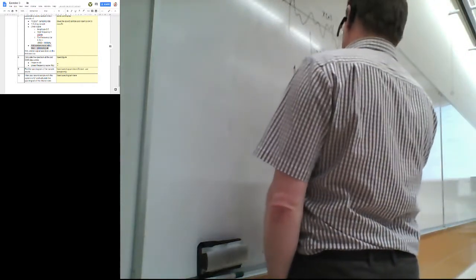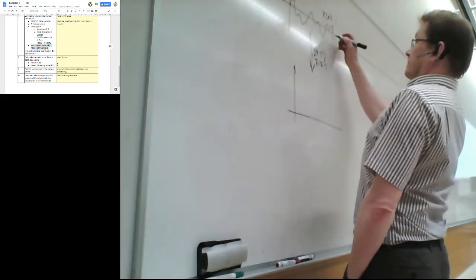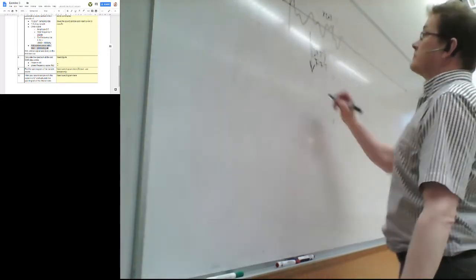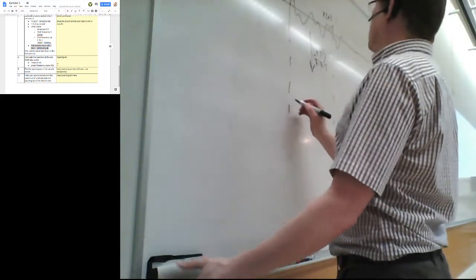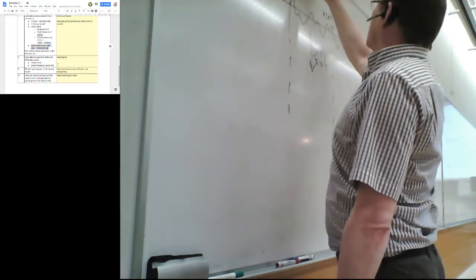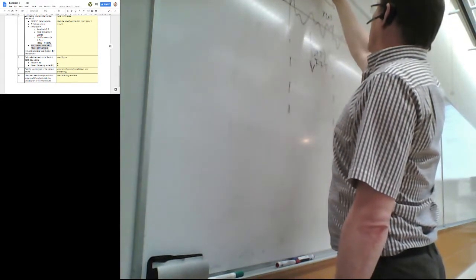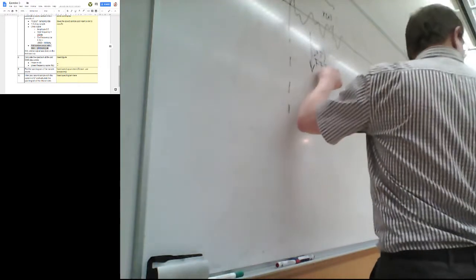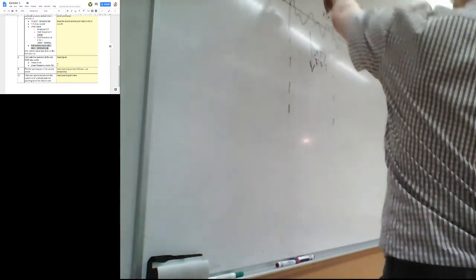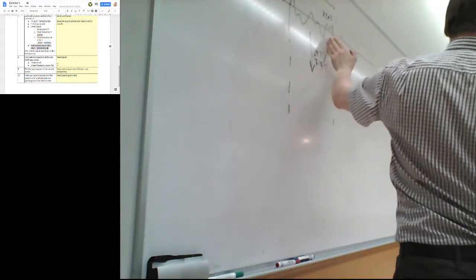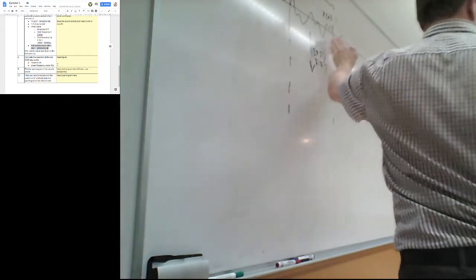But anyways, when you do the discrete Fourier transformation on that block, first it means that you must have n as 2 to the power of something. So that many data points in order to use the FFT. If you have less, basically you can do zero padding to achieve the same resolution.